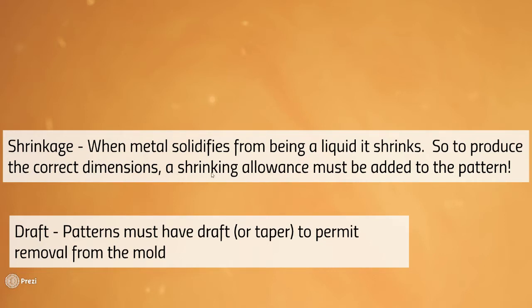That means your pattern has to be a little bit larger than you want your actual product to be, so that when the metal shrinks, it shrinks to the correct size.